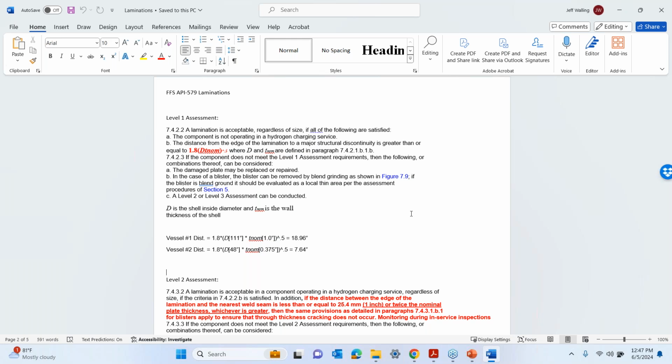Well, that can be easily answered. Yes, it does. The stress values might change depending on the year, before 99 or after 99, and the temperature. For all the basic materials, not everything in ASME, but pretty much anything you're going to have to do within this industry is in there. It automatically fills in when you're doing the calculation. You just select the material, and then depending on when it was built and what temperature it runs at, it will automatically put the correct stress value in for you.